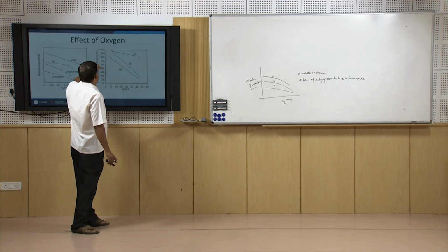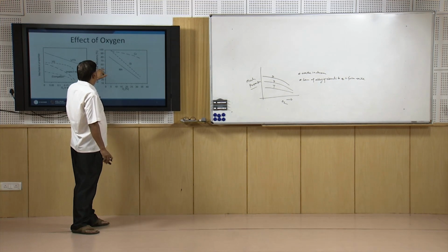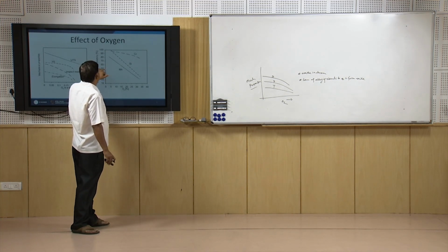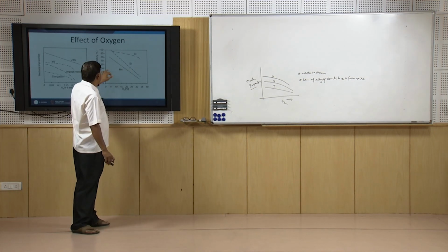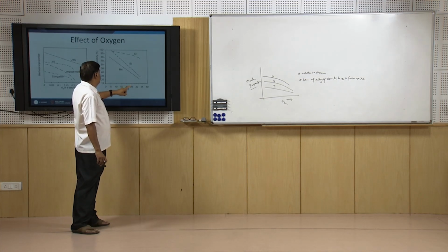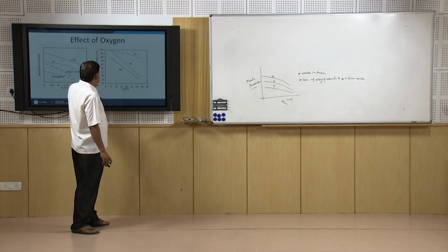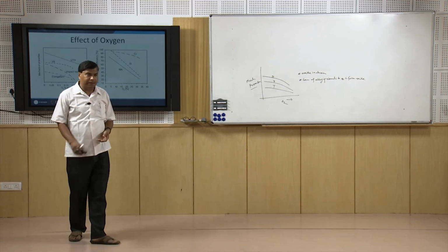For example, if the filler had 2% of a particular element, like say silicon, then for a particular concentration of the oxygen, we will see that for 25% of the oxygen, it will lead to 50% element transfer efficiency, meaning actually the weld will have just 1% of the silicon.